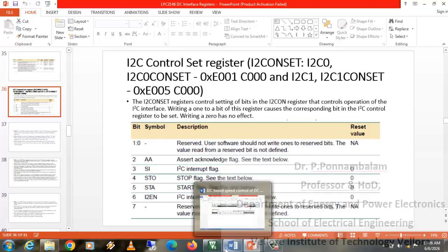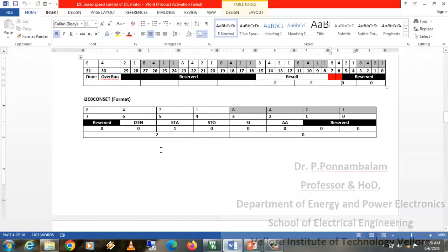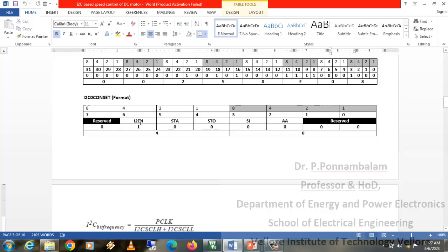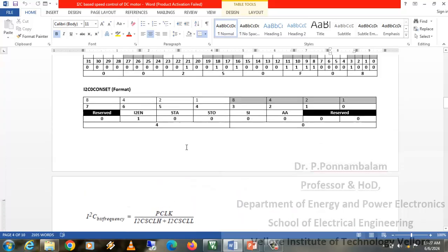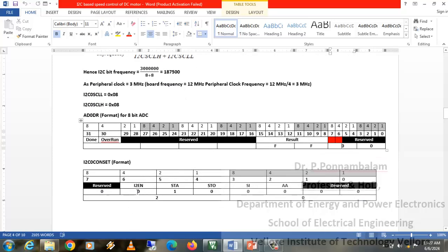In this instruction, we are starting the I2C. Already we have moved a value to I2C enable. You shouldn't be confused: since we already moved a 1, and then a 0 over here in I2C enable, will that disable your I2C? No, it doesn't.